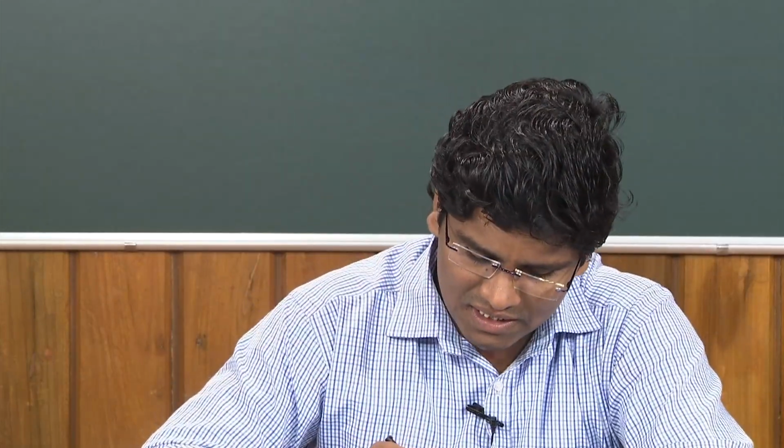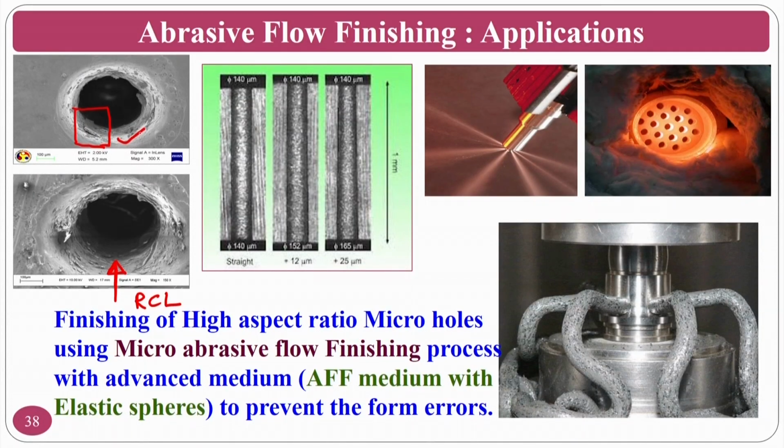As I said, casting means melting, then you just put it into the mold. Here there is no mold, but the molten material will solidify again. That is why this resembles a casting technique, and the layer formed here is a recast layer. You can see here how the recast layer is there. If you put this particular component in a practical application, it is going to fail as early as possible. For that purpose, you should always try to finish this surface, so that you remove the recast layer and the life of the component increases.